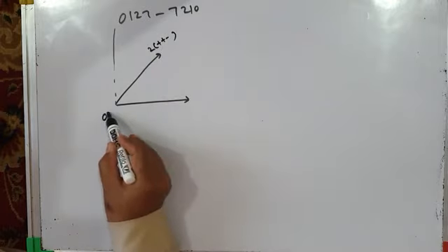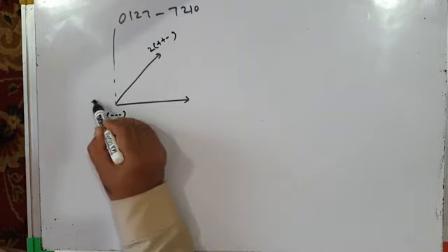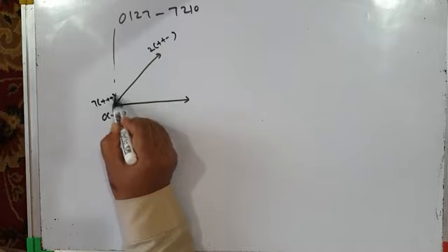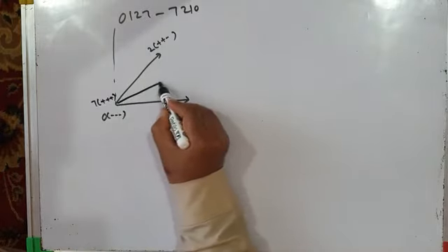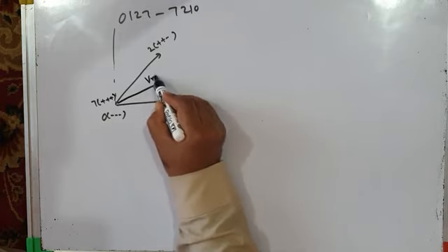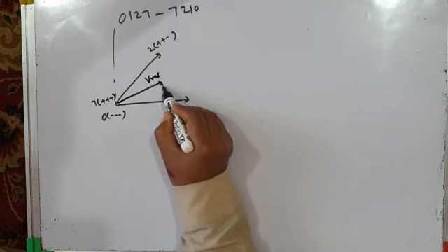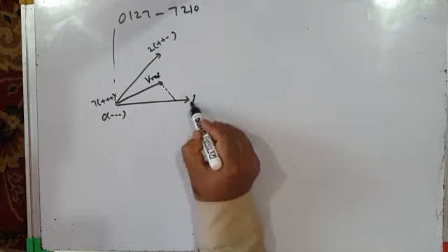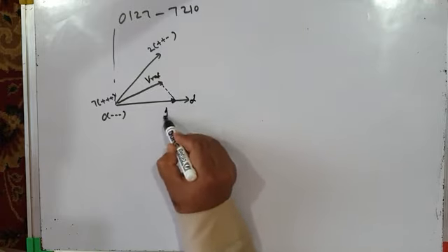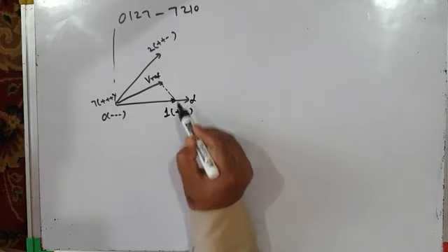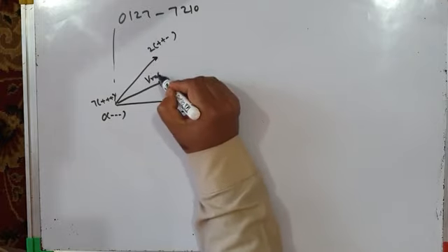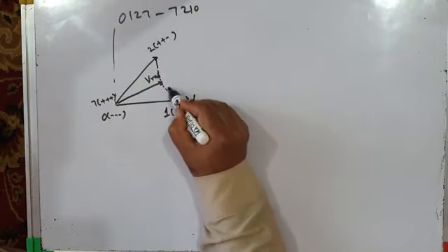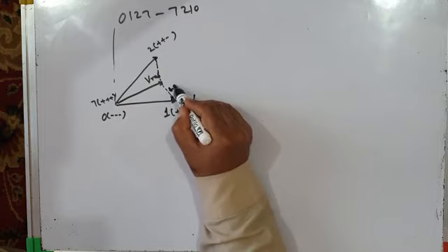We have null vector 0, minus minus minus, or null vector 7, plus plus plus. You already know. This is our reference vector, say this is Vref. This may be our active vector 1, plus minus minus. This is active vector 2. This is error voltage vector VR.